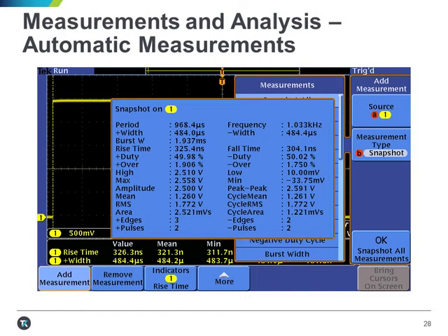One way scopes can distinguish themselves is how flexible they are to gate and make the measurements. Do the measurements happen over the whole record length, or just over the display, or just between the cursors? On some instruments, you can actually set these.